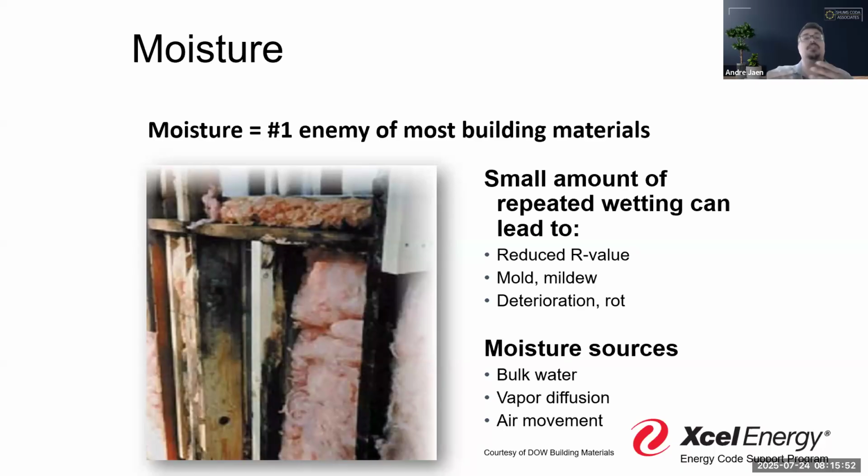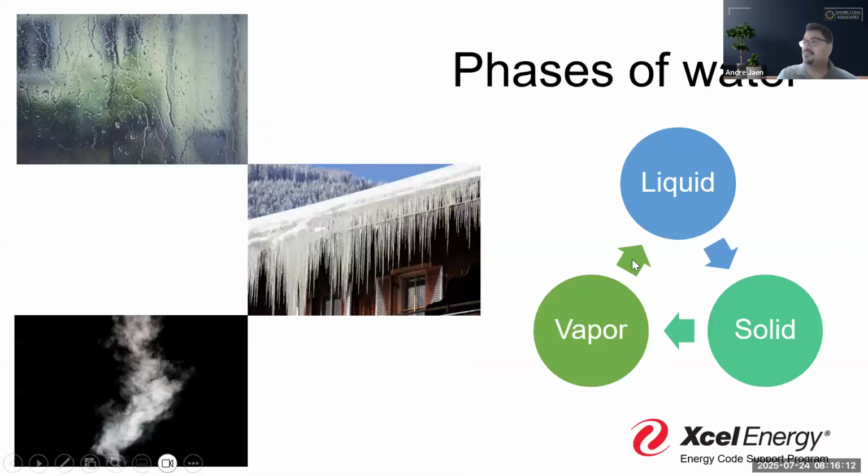And remember, the point of a good thermal envelope is to create temperature disparity, to not be the same temperature on the outside as it is on the inside. So this is a problem we always have that's endemic to what we're trying to do, just based on physics, right? And then air movement, of course, right? Air movement can always bring moisture with it. The more air can penetrate through the assembly, the more moisture that can come with it.